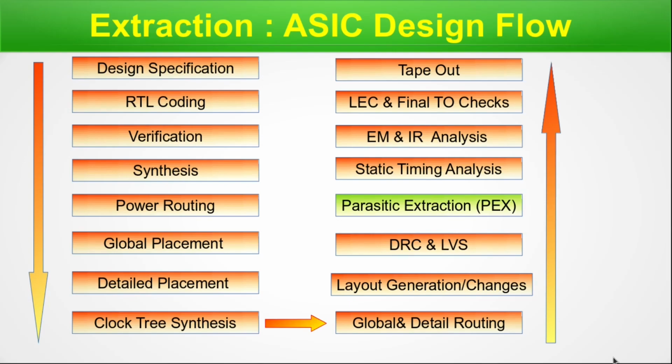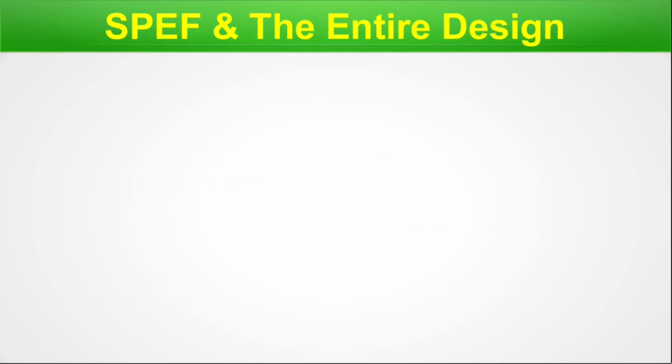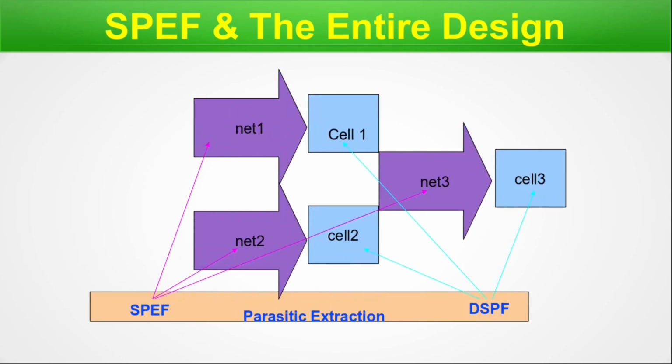So guys, we are done with this particular slide, so let's move on. SPEF and the entire design. You may wonder that we have taken care of the parasitics of the metal via interconnection through SPEFs. An obvious question comes: what about the interconnection inside each standard cell? Here goes our diagram. As you can see, the standard cells are interconnected by nets.